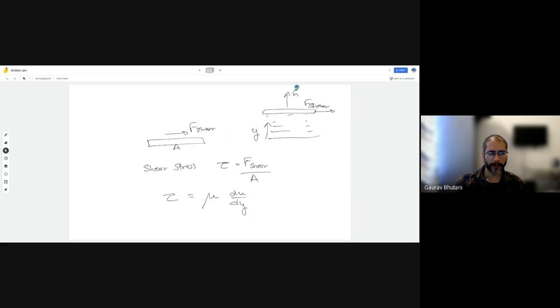Okay. So if you were to look at the velocity profile here, then what you see is that the velocity on the top is very high because the wooden plate is moving, and the layers just below that are moving slightly slowly until you have zero velocity on the bottom plate, because the bottom plate is not moving at all. So it has to satisfy that condition as well. So you see some sort of velocity distribution.